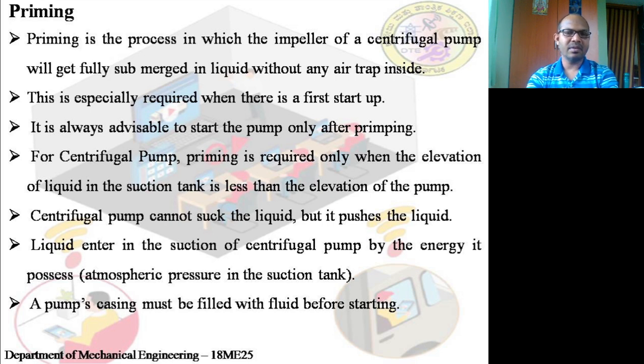A centrifugal pump cannot suck the liquid, but it pushes the liquid. The liquid enters the suction of the centrifugal pump by the energy it possesses, atmospheric pressure in the suction potential. A pump's casing must be filled with fluid before starting.